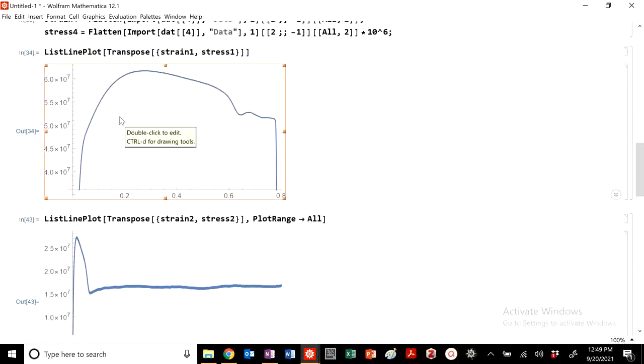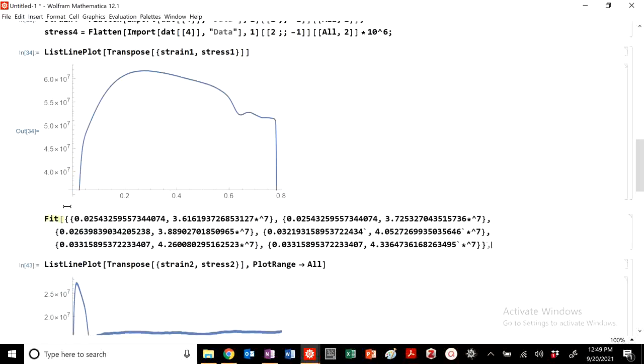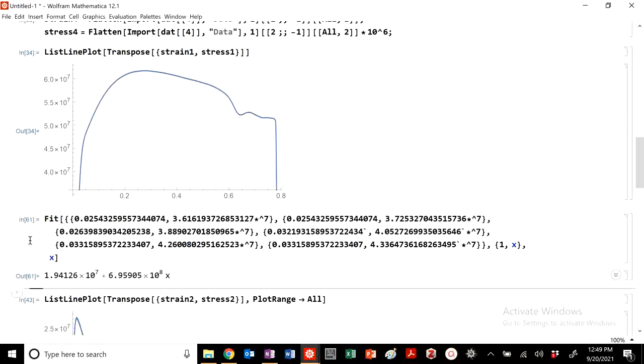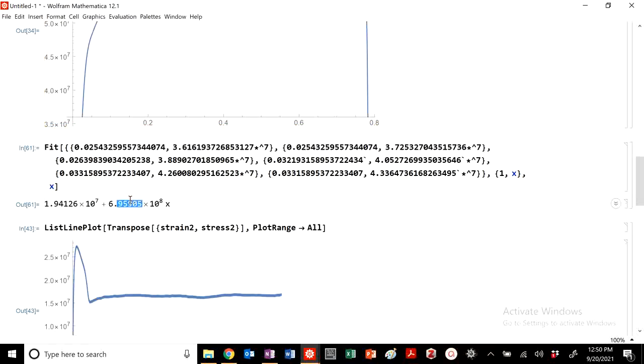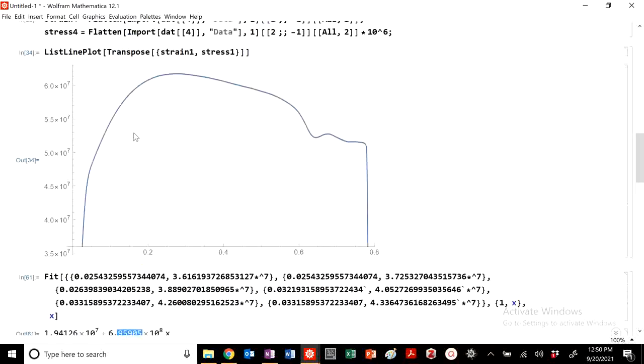So I could look at this plot, and I can do a couple of things. If I want to calculate my Young's modulus, I'm just going to grab these points. I'm going to do fit 1, x to my data for x. And I get about 60, oops, let's see here. As you can see on this curve, I get about 60, it's actually a little bit less.